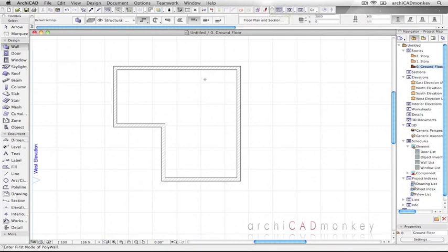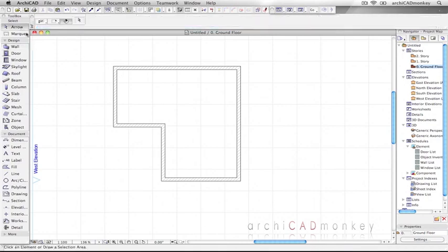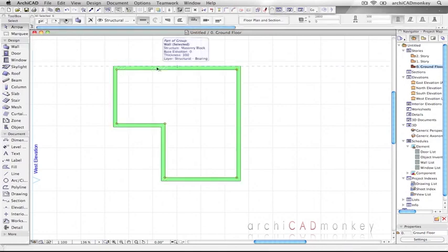Next, we'll edit the walls from the wall settings to configure the details. Select the arrow tool and click on one of the walls. As you can see, all 4 of them are highlighted in green, meaning they're selected. This is because we drew these walls as a group using the chained wall. It makes it simpler to move and edit them as a whole.